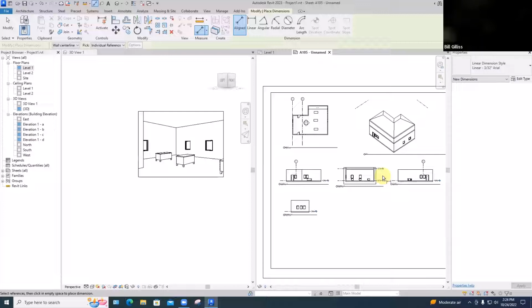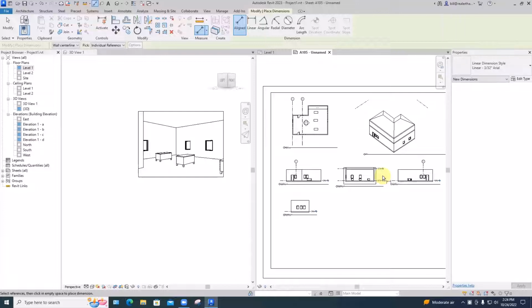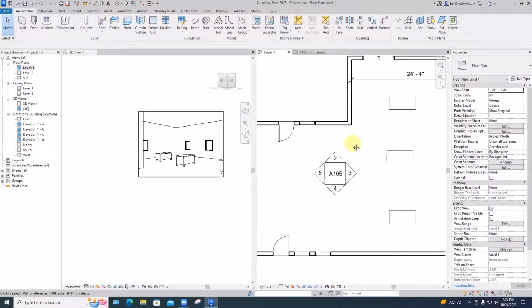And one reason for doing it that way is sometimes on a small room, let's say a bathroom, you've just been able to fit the word bathroom and the room number in on the floor plan. But then when you get to the lighting plan, and there's only like one place you can go, there are 2 lights in the ceiling and those letters are covering that up, and you have to move the room name, and it moves it in the floor plan, and now it's covering up the toilet. In Revit, you have 2 different labels in 2 different drawings, and you just put each one where it needs to be. It's very clean. Let me give you a little illustration of that.